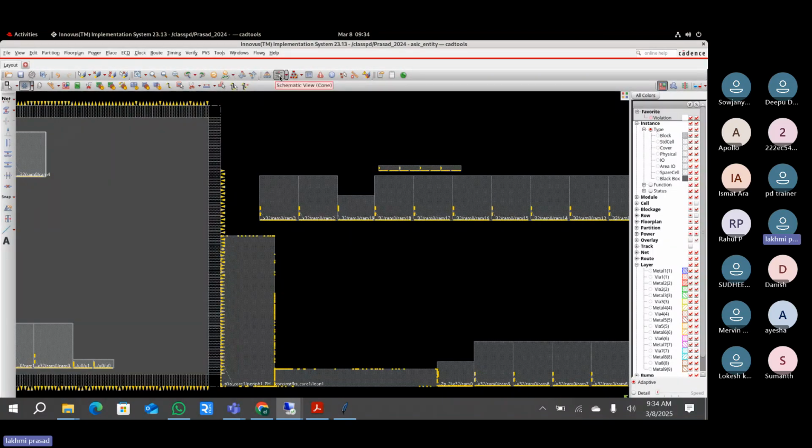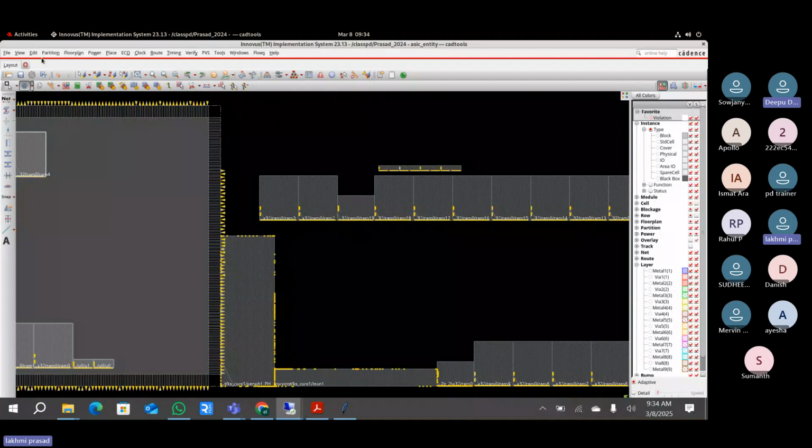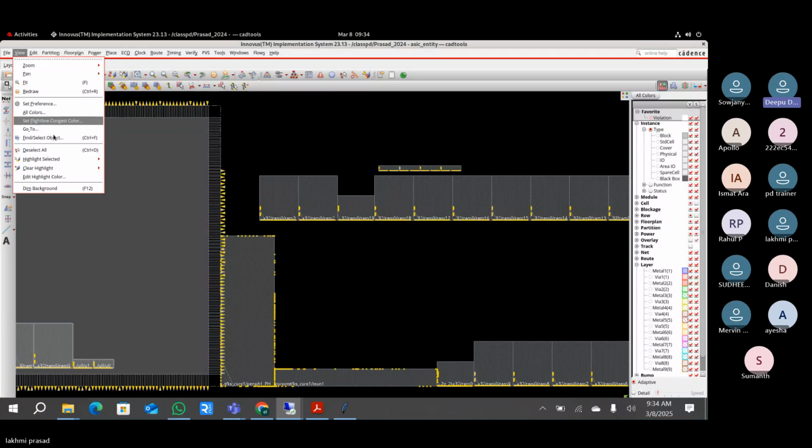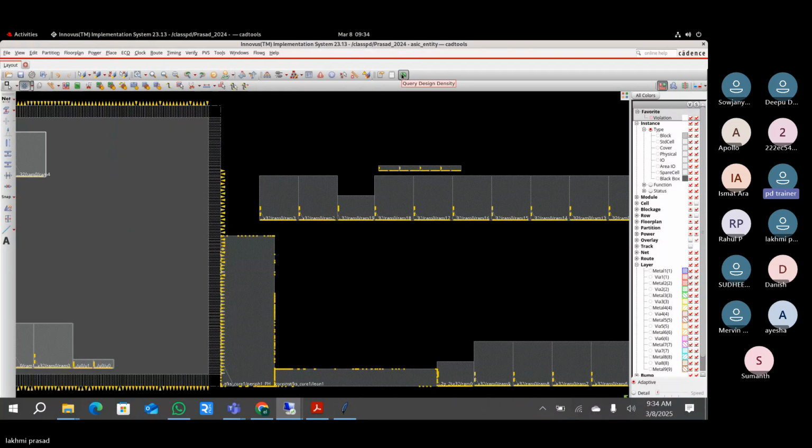And group is on the schematic board. I think it was in view, right? Blockages is okay. If somebody wanted to try for blockages, I'm telling them so that they can see parallelly. In the below row, below this row, there will be placement blockages, routing blockages. Keep going towards the left. Yeah, this is the one. Pin blockage is there.